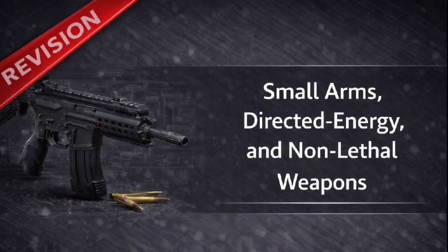So engineers harness these 2 energy sources, the backward physical push of recoil and the energy in the expanding gas of muzzle blast, to power the 3 basic systems of automatic operation. Correct. And those 3 distinct mechanical philosophies are blowback, recoil, and gas operation. Our deep dive now pivots to the engineering trade-offs of each one of these systems.